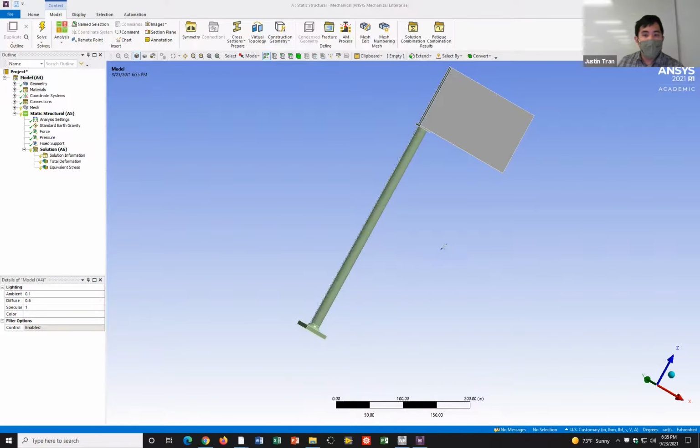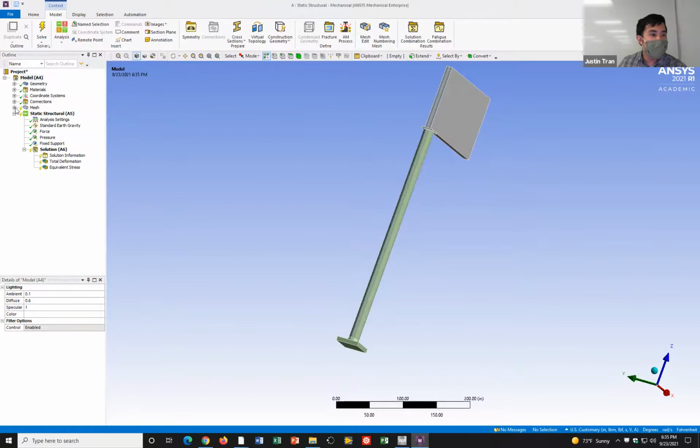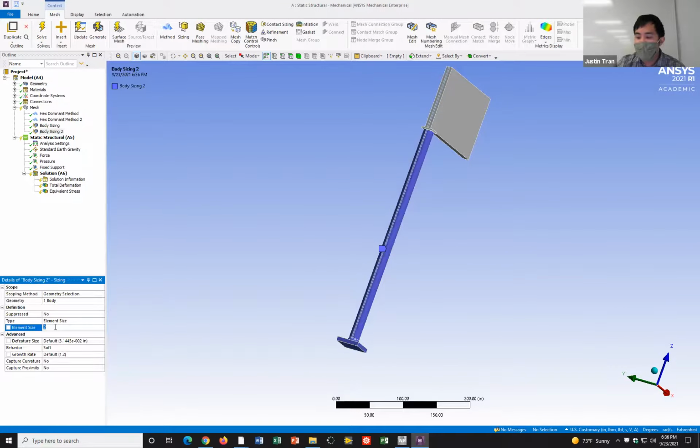All right, and so you can see here my post is a little bit thicker now, right? And so the nice thing about this is that it saved all my meshing settings and boundary conditions. And so I'm just going to hit, actually, just so we're not meshing for days, let me change this up to 3. Okay. I hit solve.